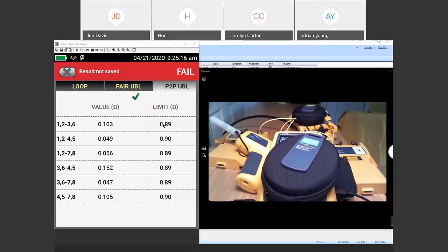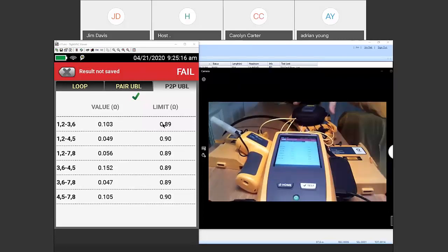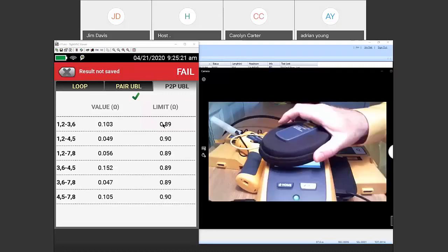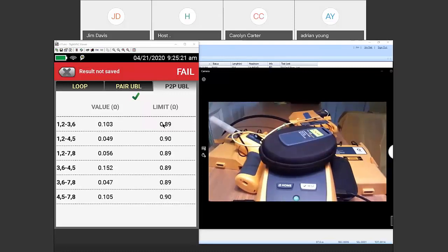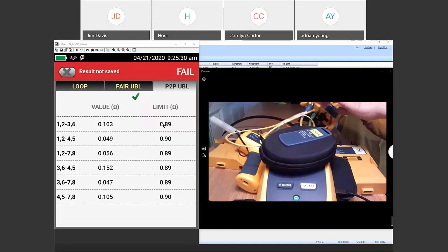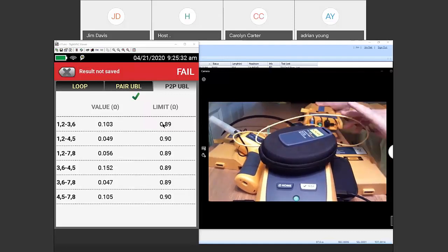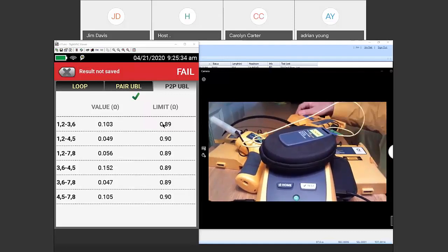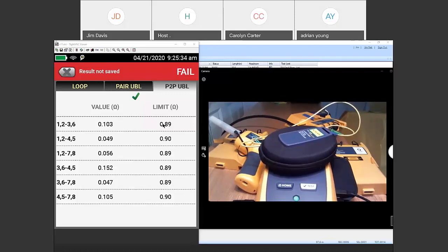The question that's coming is: most carriers use single mode with APC. I would say actually all of them use APC. Should we use APC to UPC when testing? Absolutely not. The whole point of an APC is that you want to see a very small reflection, if any reflection at all, at that connection point. If you use an APC to UPC, you're going to see a big reflectance and your customer's going to say something is wrong. So when it's APC, no funky patch cords, no funky adapters. You want to keep it APC native all the way down.